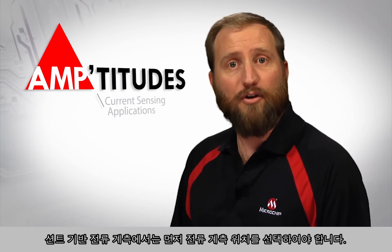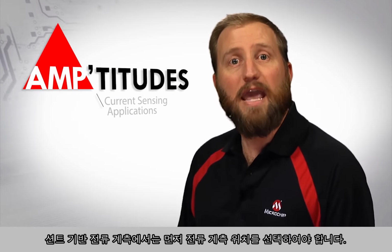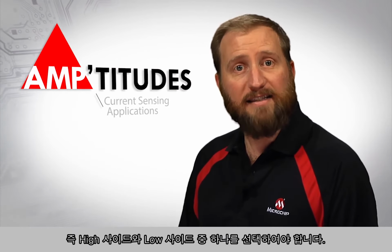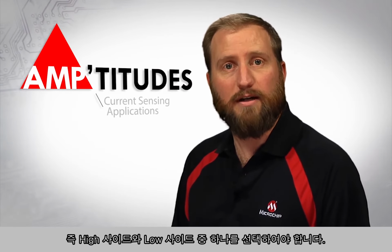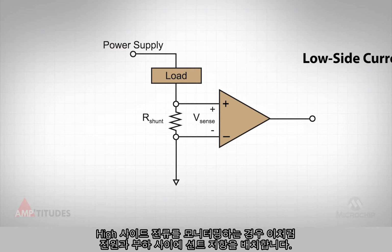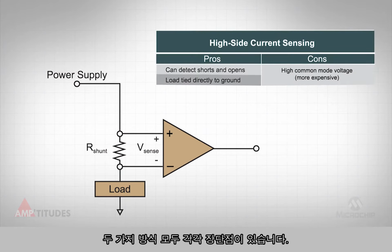For shunt-based current monitoring, the first question that must be addressed by a system designer is where to monitor the current. There are two basic options, high-side and low-side current monitoring. For high-side current monitoring, the shunt resistor is placed between the power supply and the load, as shown here. For low-side current monitoring, the shunt resistor is placed between the load and ground, as shown here. Both of these approaches have their pros and cons.